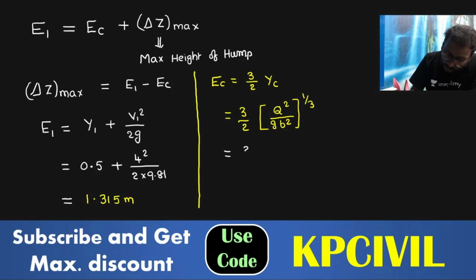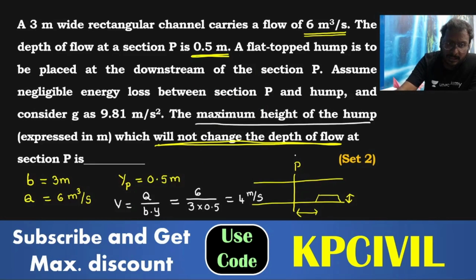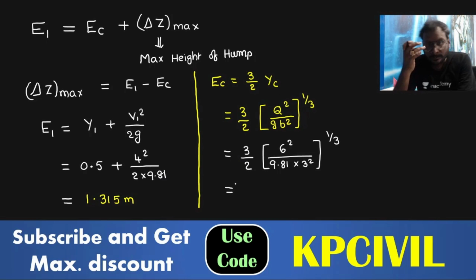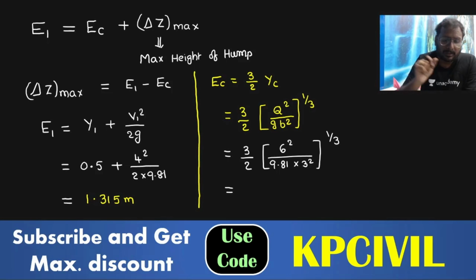EC is equal to 3 by 2 into Q 6 square, G 9.81, B, what is B? 3 meter, 3 square, whole power 1 by 3. Then what is EC, the critical energy? Calculate 3 by 2 into 6 square by 9.81 into 3 square whole power 1 by 3. What are you getting? 1.112 meter.